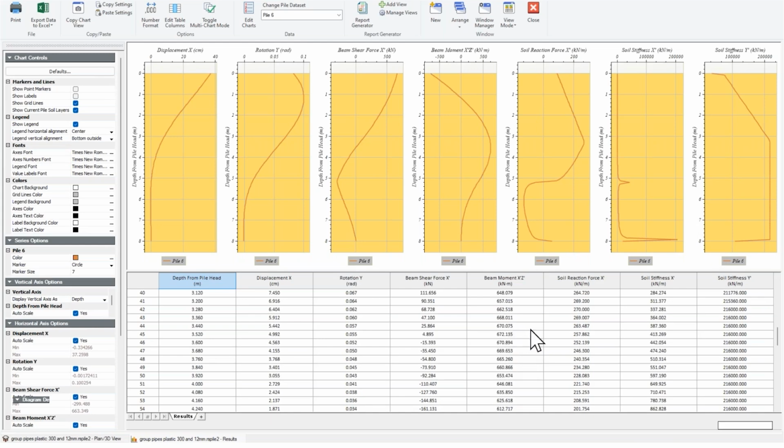And you remember the figure in the table was 1080, which means the pile is adequate if compared to the plastic moment, although it may be very close to or exceed a little bit the elastic range. Of course, if you take a larger thickness, like going from 12 millimeters to 15 millimeters, or you increase the diameter from 300 to 400 or 450, you will get better results, until you get satisfied with your displacement, and there is no plastic hinge anymore.